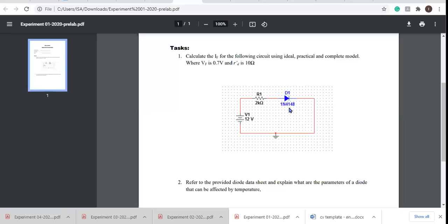That resistance has a value that is quite small. For example, here it is taken as 10 ohms. Sometimes it goes up to 50 ohms, but it has a value, right? That's why we don't have the ideal response of the diode that we are supposed to have. Practically, there is some internal resistance that causes a change in the flow of current. Clear? Okay. What about the RR?